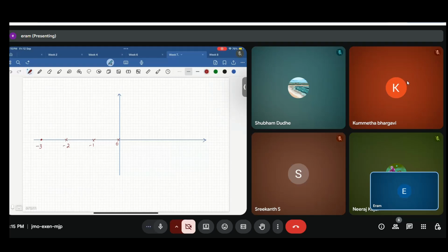Again we will have this part in the root locus and then this part. And the number of asymptotes in this case will be, now we have one 0 also, so n minus m will be 3 minus 1, which is equal to 2.